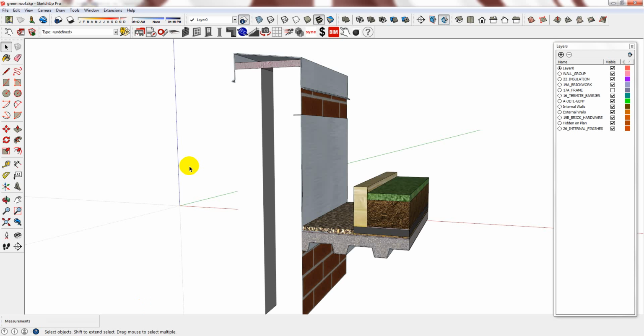The second method is to create 3D details for the junctions where you need them only. So you would base it off of the Plusspec for SketchUp model. You can model it either off to the side, or you can create it in a new SketchUp and Plusspec file. And then what you can do is you just reinsert it.